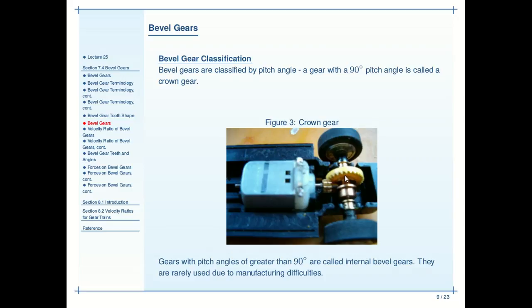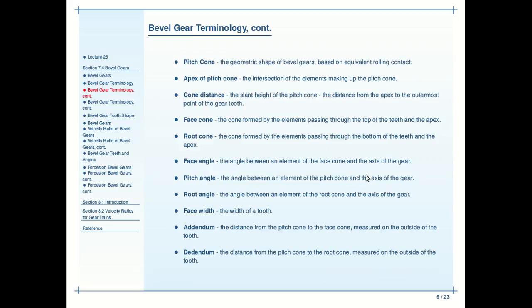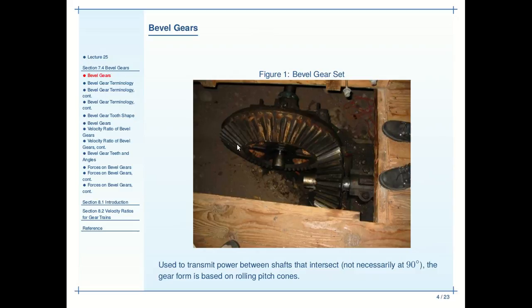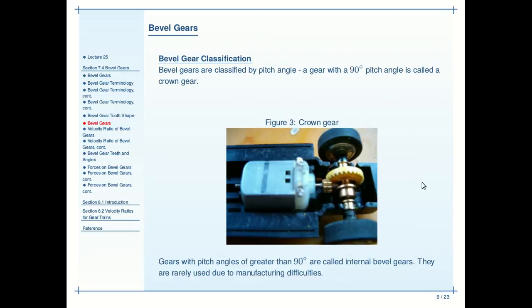This angle can change. Generally, for the kinds of bevel gears that you find, that angle is less than 90 degrees. So you get an angle like this, a pitch cone that is positive. You can actually have that angle be greater than 90 degrees, so the teeth then would be aimed in, and the apex of the pitch cone would be beneath the gear instead of above it. That's generally not done because that kind of gear is very, very difficult to cut. But obviously, as additive manufacturing becomes more common, that becomes easier and easier to deal with.